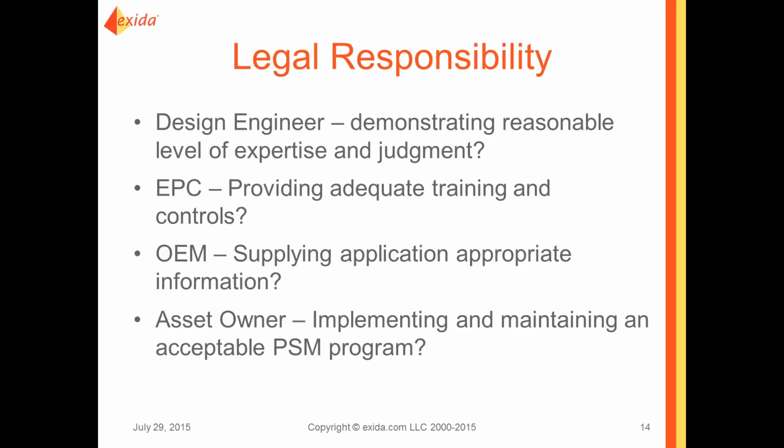There's a legal responsibility that comes with this as well. Design engineers need to demonstrate they're using a reasonable level of expertise or judgment. EPCs need to provide adequate training and controls for their people doing these designs. OEMs need to supply data that is suitable for the application the devices are going to be used in. A solenoid could be used on a bottling line cycling every couple of seconds, or it could be used in a refinery where it's going to sit for 12 or 24 or 36 months and not cycle. The failure modes and failure rates of those two applications are dramatically different.